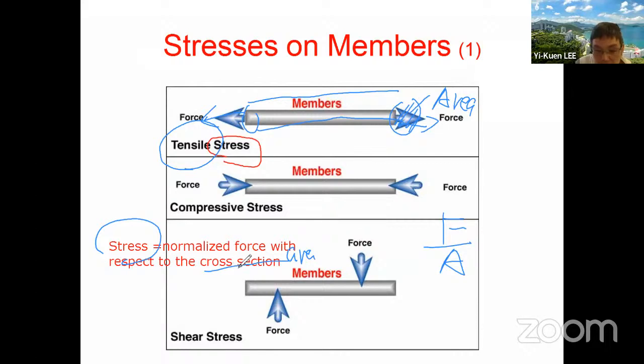In this case, it would be important for us to look at whether the mechanical design of this structural member of the building is okay under many different loadings, with the stress not too big, typically smaller than some maximum allowable stress, right? Usually we use some symbol, for example, sigma, and we make sure that this sigma, this demand stress, is below the maximum allowable stress of a certain material.